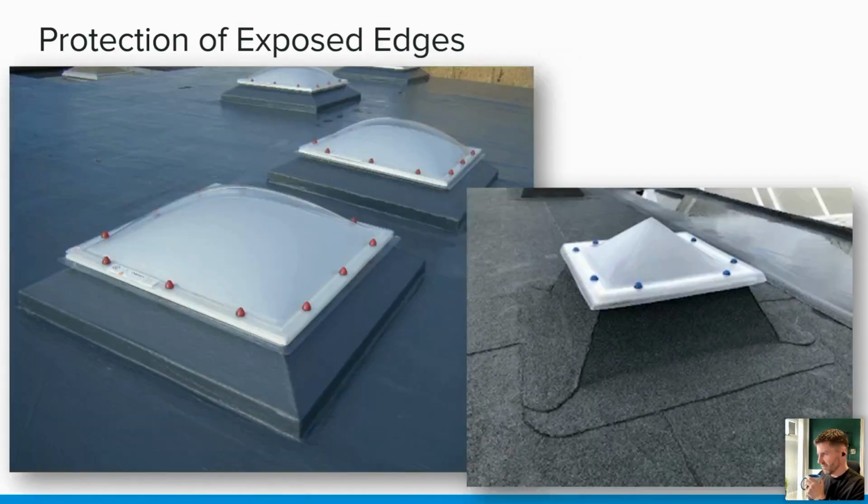What should that roof light have looked like? Well, this is kind of what we were saying. So the waterproofing goes up and underneath, and it finishes underneath that flashing detail, that preformed capping over the top there. So it's got some protection.